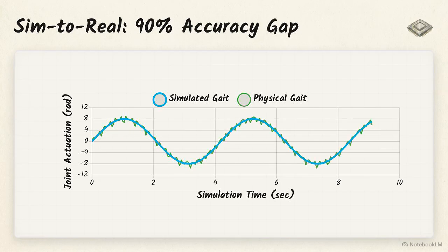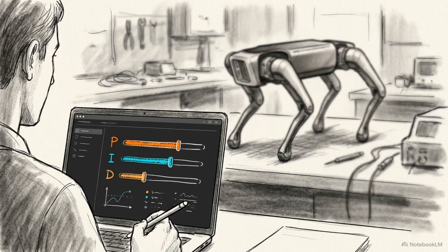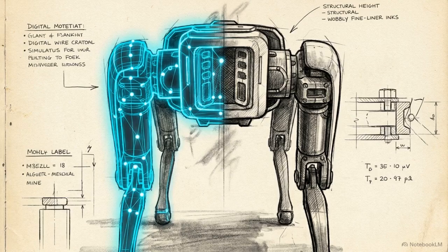Even with a specialist engine, a simulation is still an approximation. Inevitable factors like real-world sensor noise and hardware variance mean you will still need minor manual PID tuning once the robot is on the floor. But by strictly configuring Dart and eliminating the physics engine as a hidden variable, you make the sim-to-real gap manageable and your robot's behavior predictable.